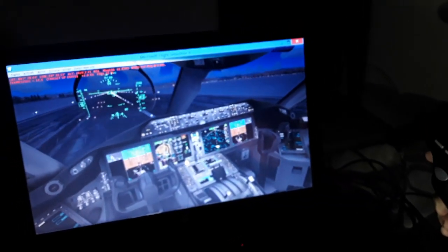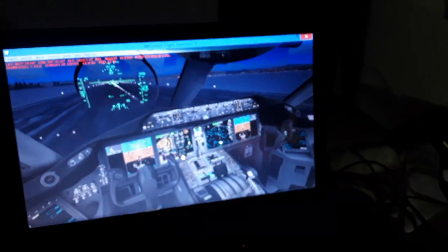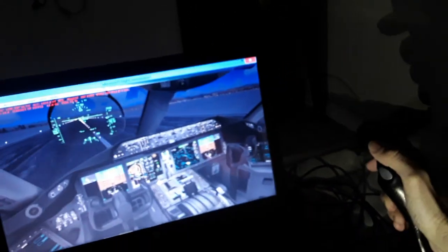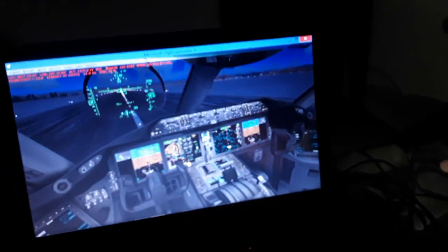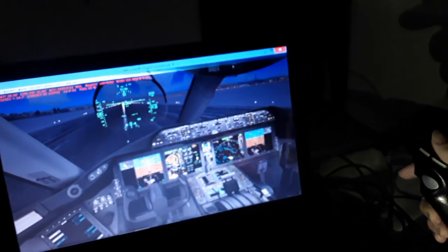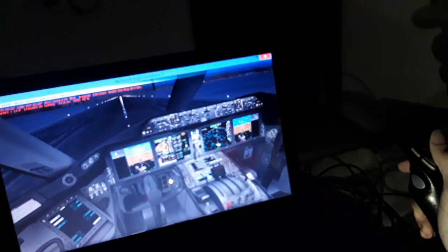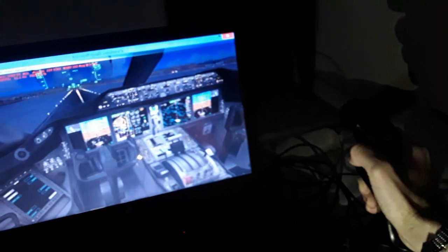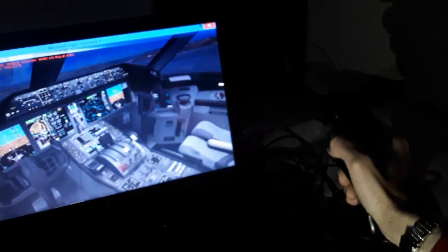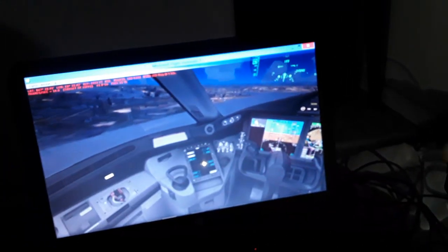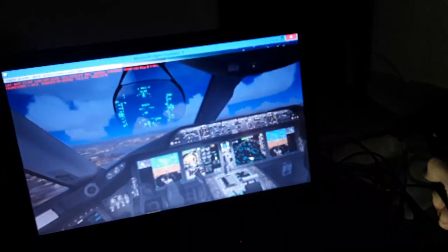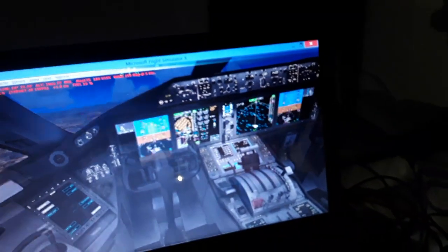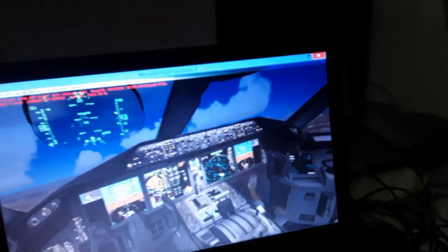Full takeoff power. Align with the rudder pedals. So we have 120, 130 V1. We rotate slightly like this. So pitch up slightly. We have the positive rate of climb. So landing gear up. Over here, landing gear retract. Keep climbing.